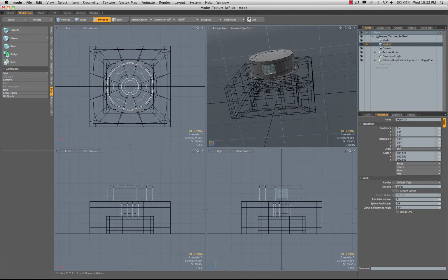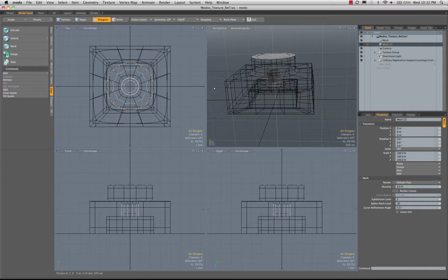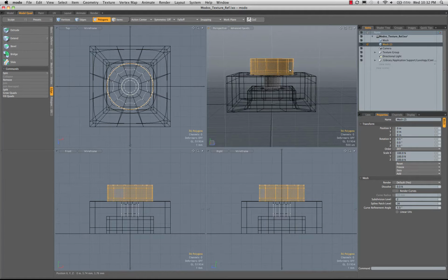To start myself off, I'm going to select this loop and then shift up arrow, and I'm going to copy that, and then I'm going to hide what I've copied. I'm doing this so that I can paste in some geometry and still have control over it, and be able to actually grab it, without it just meeting up with everything else and duplicating my polygons, causing a big nightmare that I'll end up having to run some kind of a cleanup script on.